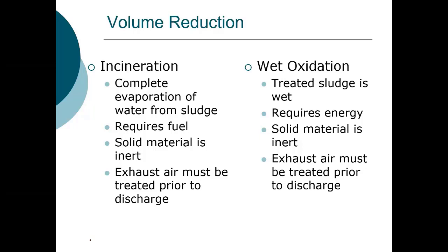So they no longer incinerate, but one can incinerate biosolids. It's highly energy intensive because one has to completely evaporate the water from the sludge. And if your sludge is only 5 or 10% solids, that's a significant amount of water that one has to evaporate. So it requires fuel.